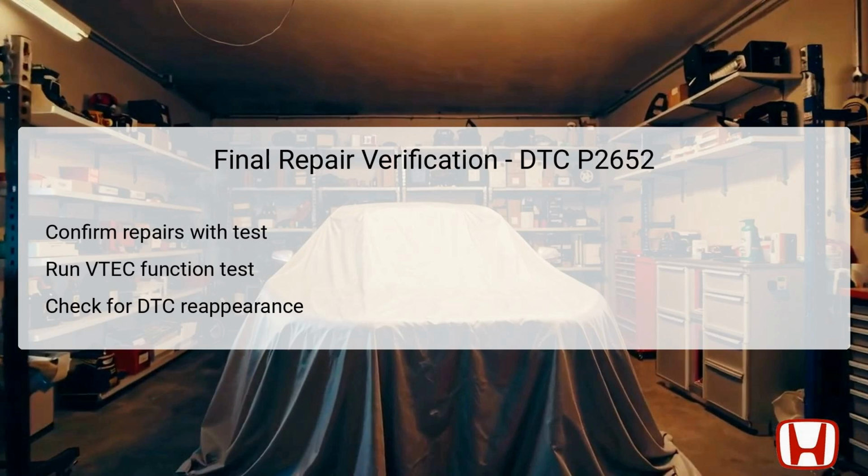This begins with running a VTEC function test using the Honda Diagnostic System, HDS. This test will ascertain whether all VTEC-related systems are functioning correctly. After executing this function, clear any DTCs and run the system to observe if the DTC reappears. If the code does not return after multiple tests, it confirms that the problem has been adequately addressed. Following this final verification, it's advisable to ensure that all connections are secure and that no leaks are present in the system, thus safeguarding against potential future issues.